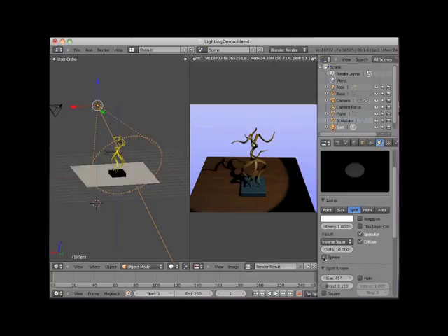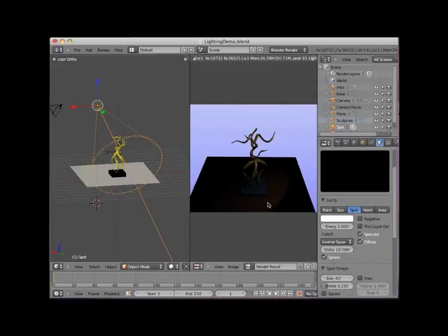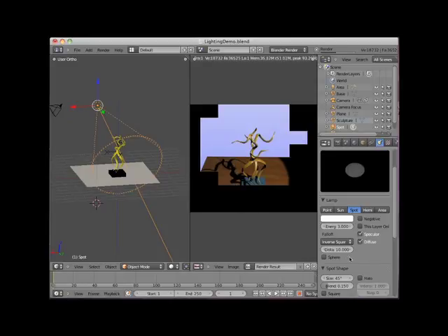I'll checkmark the sphere checkbox and render the scene. Because the sphere linearly falls off from full to 0 over the distance length, the object illumination is much dimmer. I will uncheck the sphere checkbox and raise the energy level to 3 to compensate for the shorter fall-off distance of 10, and then render the scene.